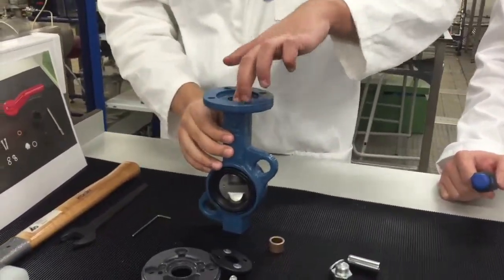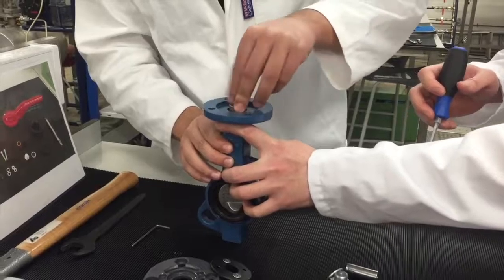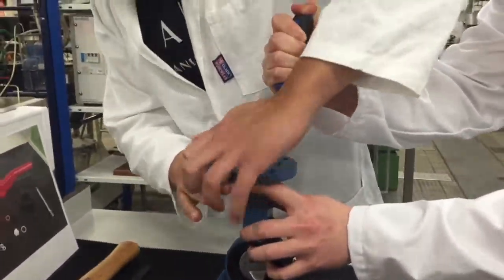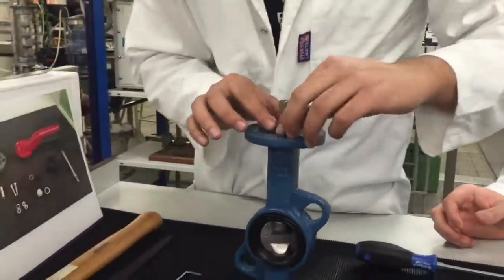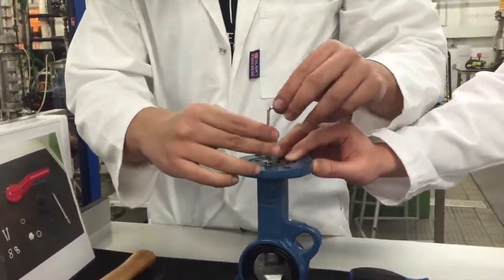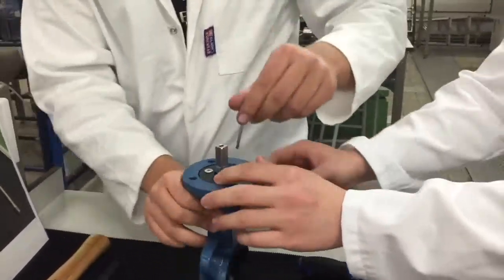There are three main important components to the butterfly valve: the disc, the seat and the body. The rotational disc located at the bottom of the valve is used to control the flowing material in the pipe. The disc is always in the passageway, but because it is relatively thin, it offers little resistance to flow.